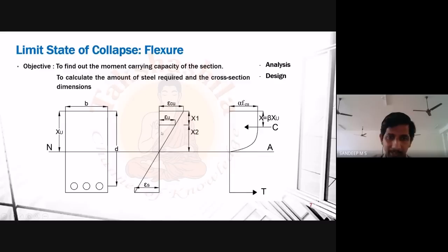Again here I have a linear variation of strain, and finally at the midpoint. Please note, there is a slight mistake here. This line must actually come at this horizontal level, at the centroidal level. There is no mistake in extending this also: once we have a strain value like this, we can extend it up to the bottom of the beam. Based on our first assumption, that plane sections normal to the axis remain plane even after bending, we have a linear strain distribution. So this figure represents the variation of strain across our section.